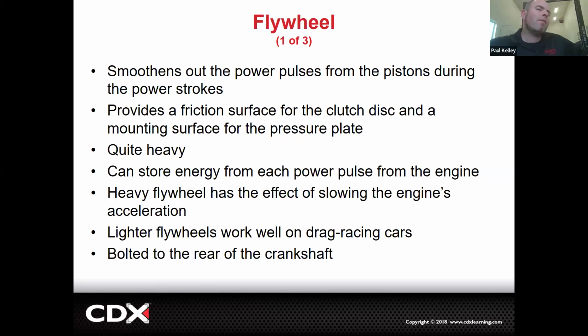Like, you can just feel it. You feel connected to the engine more. You can feel the pulses. You can feel the road when you do those coilovers with all the polyurethane bushings, right? That's all harshness concerns. You're not isolated from the action so much. Cool. So lightweight flywheels are good if you want the car to rev up quicker, because it doesn't take as much time to get the mass moving. Lightweight flywheels are not good for harshness. Got to pick one.